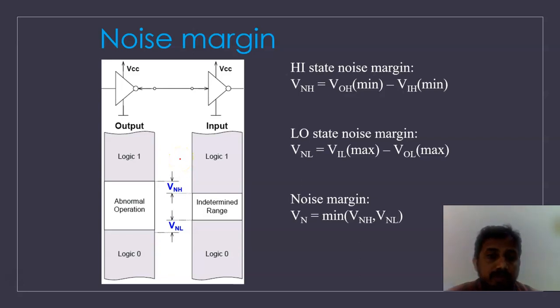The next one is noise margin. Noise margin is one of the most important key factors, because if any small noises or abnormal changes in the voltage or output occur, how would these be considered as a high voltage or a low voltage? Here we take two things into consideration: the input and output voltage levels decide the noise margin.